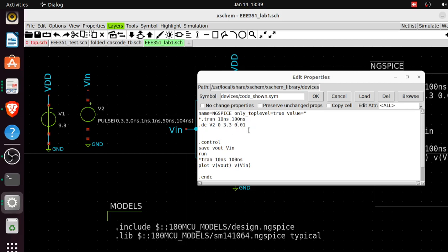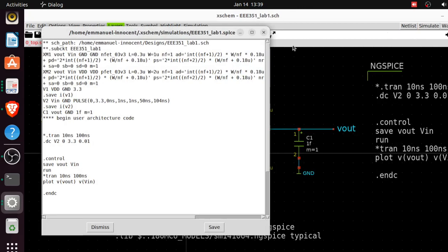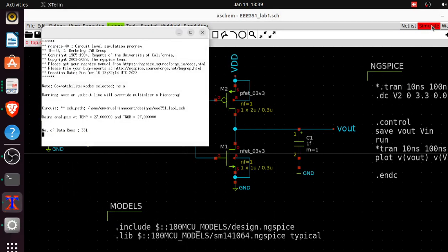Then the increment: the smaller the increment is, the smoother the sweep. So for the best graphical look, you make the step very small. For mine, I've used 0.01. Then you can go ahead and plot the input and plot the output. The netlist has no issue, then simulate.